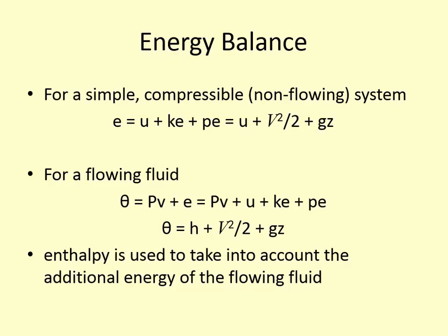Ideal gas law, we do see that, but that's not really an energy term. That's just a correlation of properties. I'm talking about boundary work, right? So it's similar to boundary work, but instead of at the boundaries, it's inside the system, because this fluid is moving through the system. Just like in our closed systems, when our boundaries started moving, we had an additional work term. That's analogous to this.